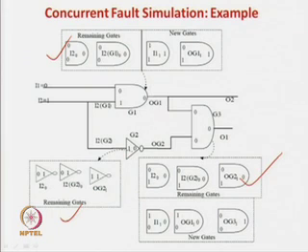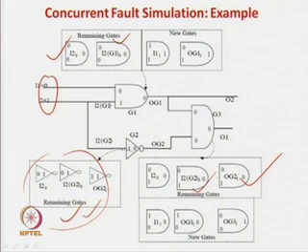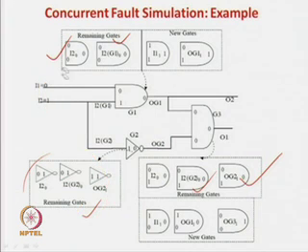Now, there is a small thing you have to do. So, what advantage have we got? We have just converted what you can call concurrent fault simulation, as we are retaining the information about the gates. So, for the new change in input, without doing any recomputation, we can find out this one, this one, and this one without any computation, and here some small computations are required. So, we are reusing the information whenever the pattern is changed, but now some new faults will also get added. For that obviously you have to do the recomputation.